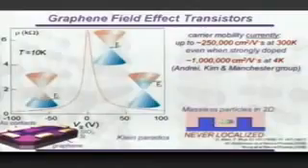The problem is that those quasi-relativistic particles always travel with their own speed of light, and they cannot be stopped. The very reason which gives you this very good conductivity also tells you that it cannot be stopped. If it cannot be stopped, it means that current cannot be completely quenched, and every single transistor needs to have two states.